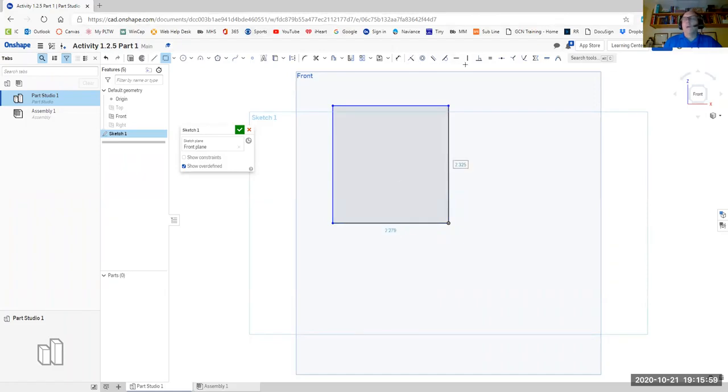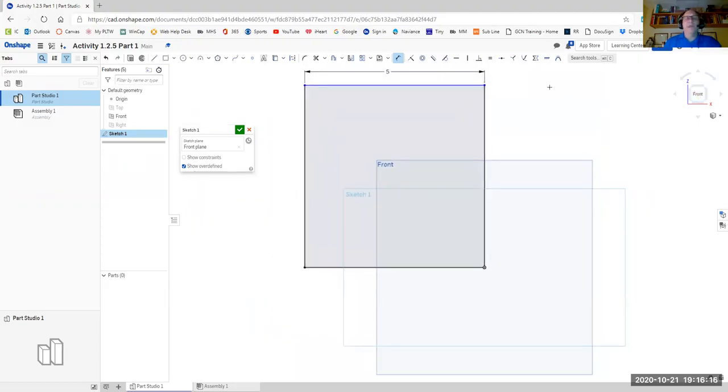Now, on our drawing, it says the diameter of our part is 10 inches. So we want to use half of that because we're going to be doing a revolve. Let's go up to measure. Let's click on our top line, come up here. So half of 10, we're going to go 5 inches. I'm going to hit my front so I can see everything again, and we need to give it a height. So I'm going to dimension the height of my object, and our drawing shows that it's going to be 4.5 inches tall.